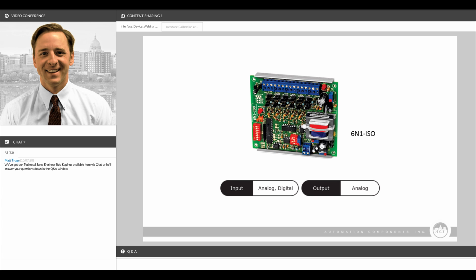So you can have multiple inputs come to this device, and you can isolate the highest or the average. So you can average temperature sensor or temperature readings between multiple rooms, or you can output a signal based on the highest reading, or trip a fan based on the highest reading or the lowest reading. So this is a simple device that allows a number of different control options from 1 analog or up to 6 analog inputs and 1 analog output.